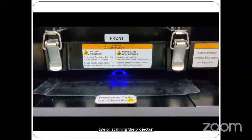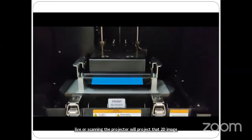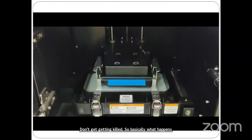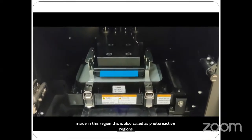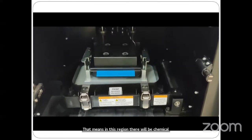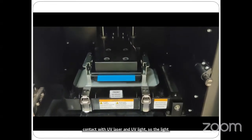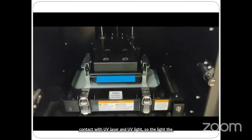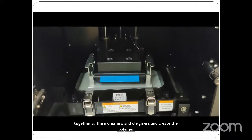The projector will project that 2D image, and it's getting cured. So basically what happens inside this resin, which is also called a photoreactive resin, is that this resin contains chemical monomers and chemical oligomers. When it comes in contact with the UV laser or UV light, the exposure to light will cross-link all the monomers and oligomers together and create the polymer. This way, the polymer is created and it solidifies. That is called curing.